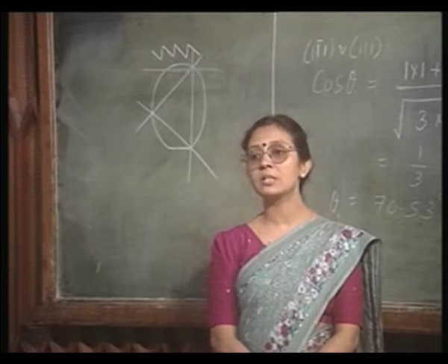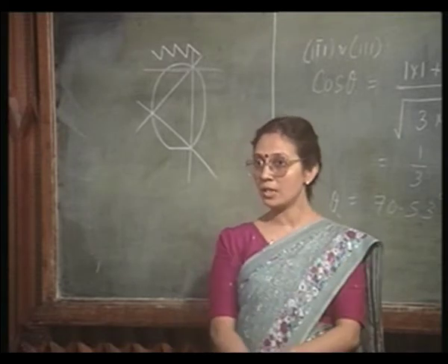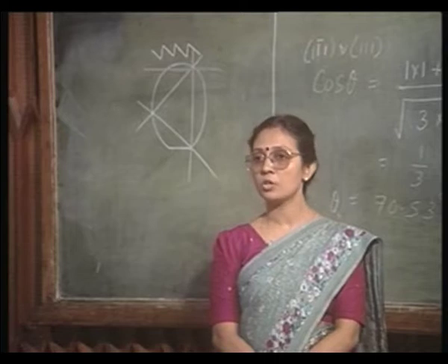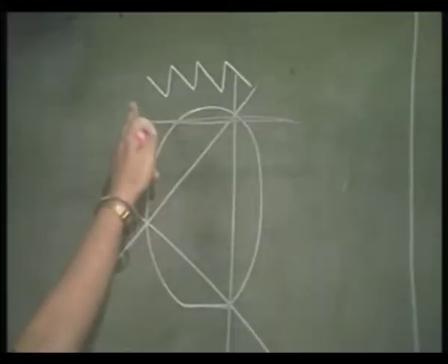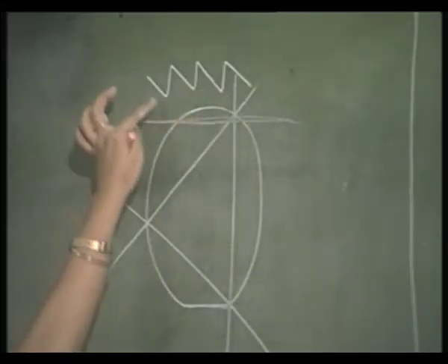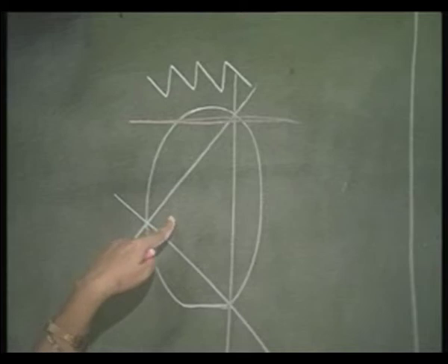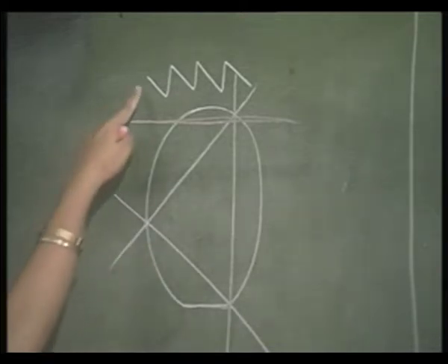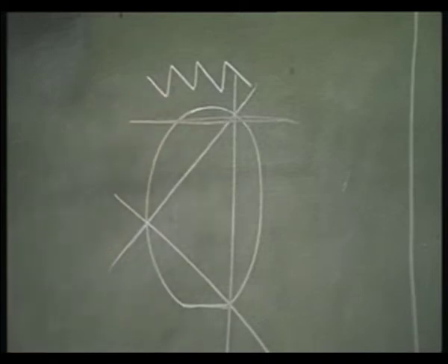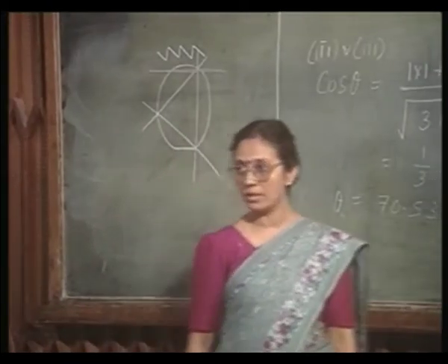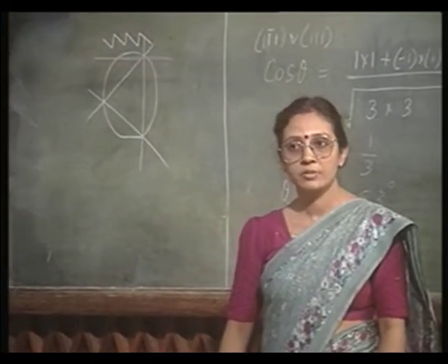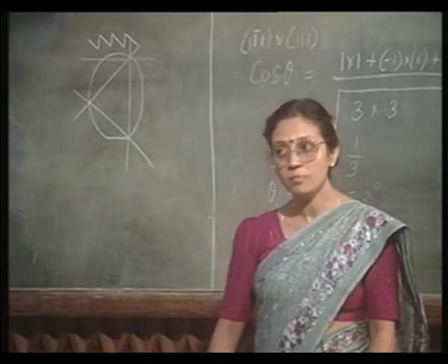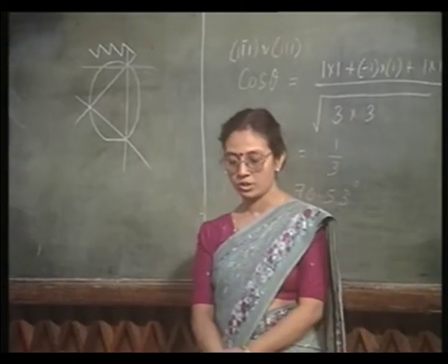But when you try to cleave in a direction perpendicular to your first scribe line, it is not going to cleave cleanly, instead you are going to have a fine zigzag pattern with each line referring to this 110 or this 110 lines, right. That is what I meant, each zig and each zag corresponding to 110 directions. So, it is a bit difficult to cleave the 111 wafer in mutually perpendicular direction.